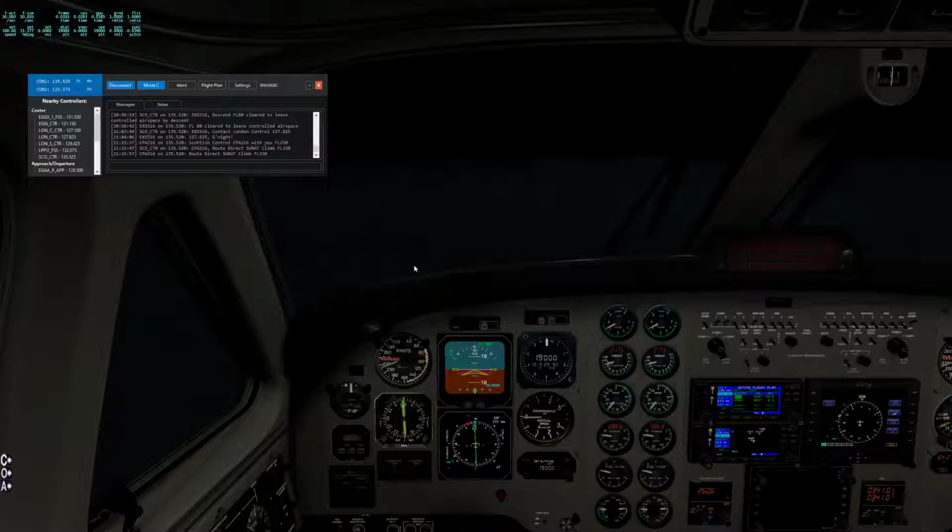And I'm now trying to work out when to start to descend to be at 8,000 feet at the right time, and there's no need to do anything. In fact, there's no need to do any other calculations. I've already worked out that if I want a steady descent from 19,000 to 3,000, I start at 60 miles, which, by the way, if you look at the VOR reading is coming up,